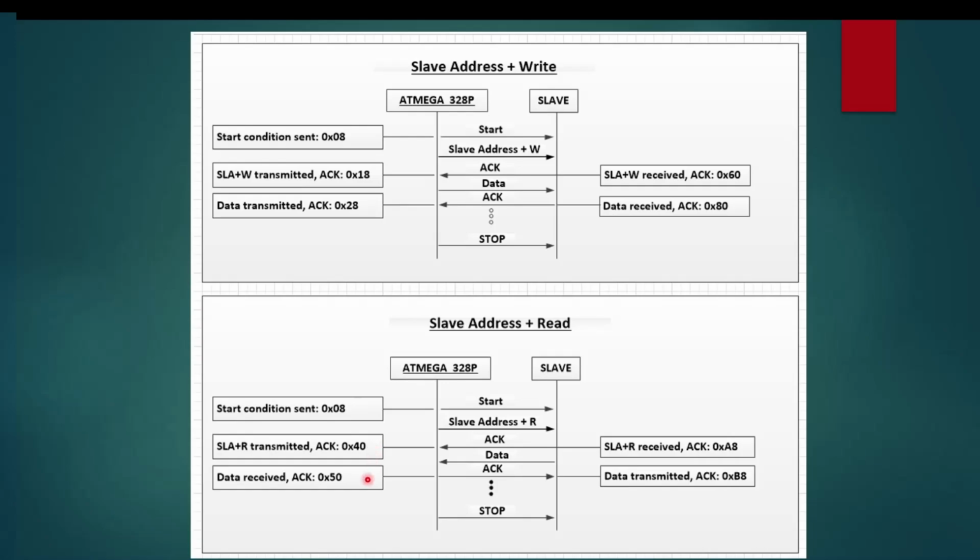At that point, the master is going to start monitoring the status register, and every time it gets a code 50 hex, it knows that data has arrived, so it has to get it, and it also knows that the data was acknowledged. It will continue to do this until it has received all the data that is expected. At that point, it's going to send the stop command, which releases the bus.